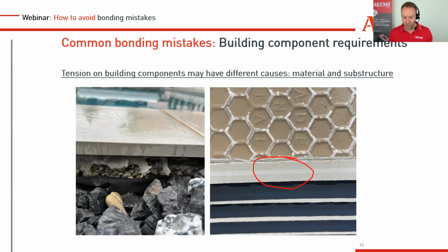So it's definitely harder here than here, and maybe different here. And then you have humidity, then you have temperature, and then this thing behaves like a sandwich. I'm not sure if all the ceramic manufacturers are aware of that. And then it tries to bend. Now when you lock that with a mitred bonding, then you will have a lot of tension and can create some problems. So if you're not sure if your ceramic or your stone is doing that,